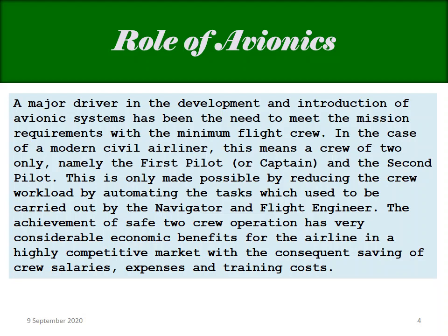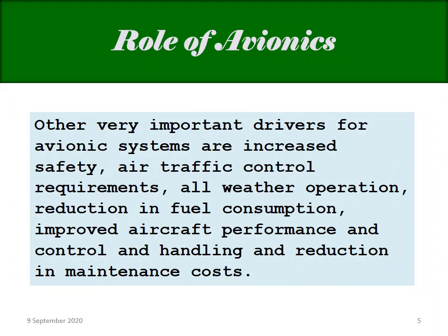So computers now actually fly the aircraft. It's not just the autopilot holding the cruise or the altitude. It's much more, because whatever disturbances the aircraft may encounter, there's a computer which monitors all of that and provides corrective movement of the control surfaces, which normally a pilot would do. So there's a computer actually flying the aircraft. All of this has been made possible by avionics.